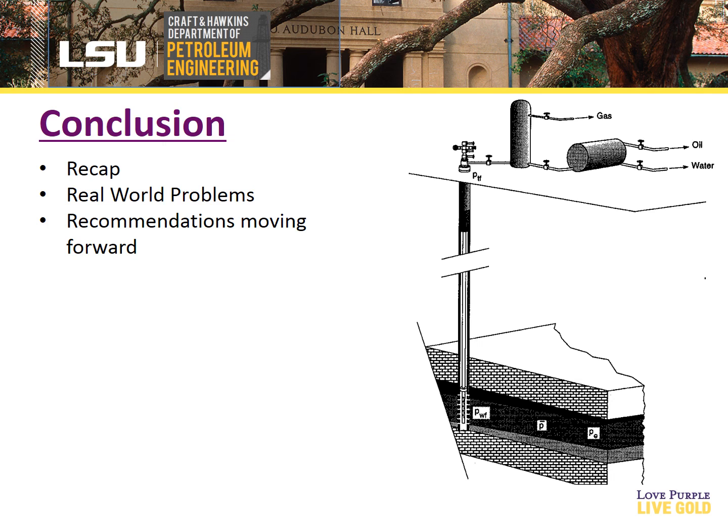In addition, the reservoir is depleted by 2 wells in approximately 3.5 years, but there are some real-world problems that must be addressed. It is not realistic that this reservoir will obtain 100% sweep efficiency. Also, tubing velocities are extremely high, and therefore the erosional velocity factor needs to be considered more to protect the integrity of our production equipment. Likewise, sand production and collapsing of our wellbore are particularly likely with such high depletion rates and pressure drawdown.